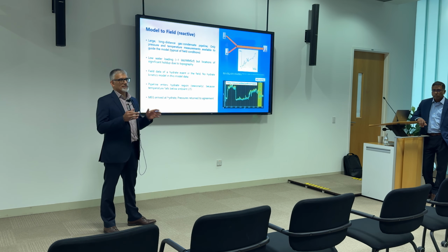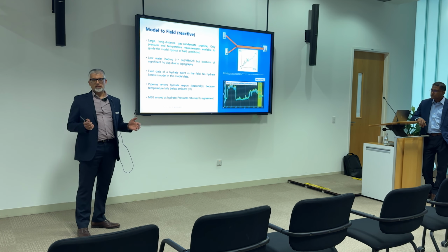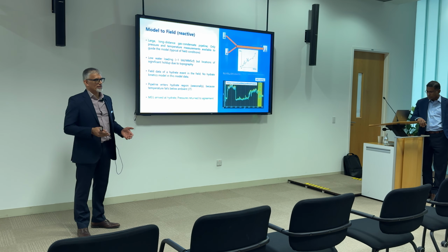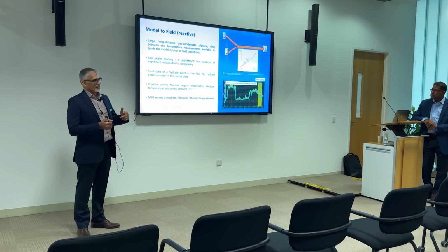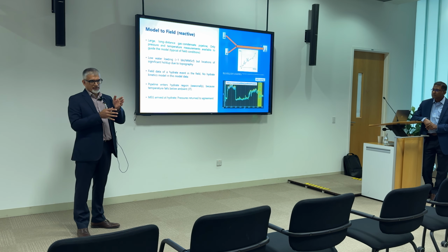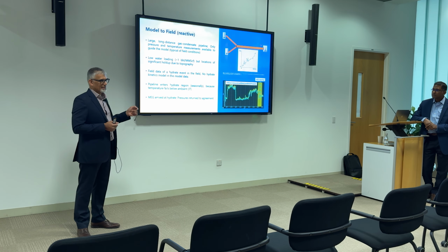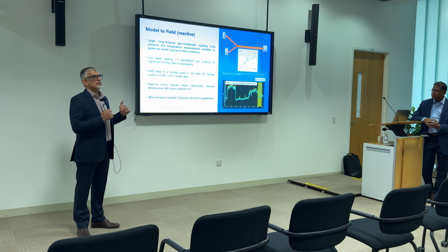So this approach is for real-time monitoring, where everything in that simulation can be tuned. When you do a design, you know exactly what you're designing for. Somebody says, this is the amount of gas I've got, this is the molecular weight, this is the composition. In reality, you have no idea what the composition is. So what you do is you run a model based on whatever information you have available. You look at reality, and if you see that the pressure drop is too high or too low, you can adjust the correlations. So that's the advantage of having a model where everything is tunable.